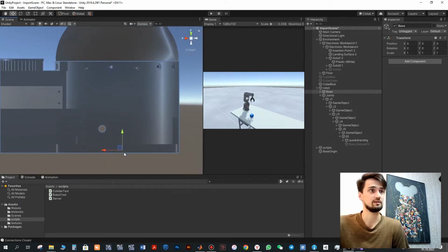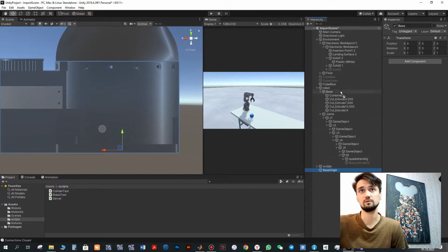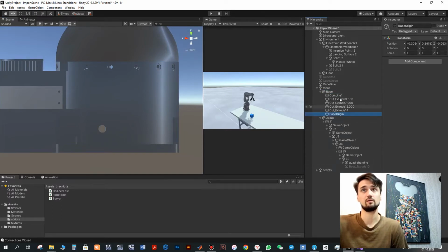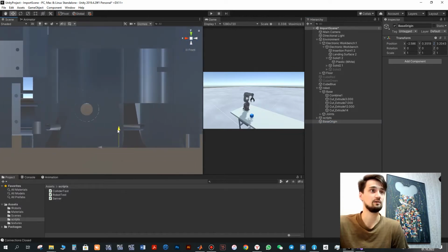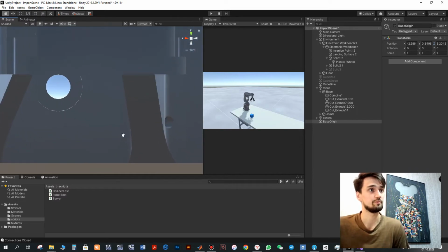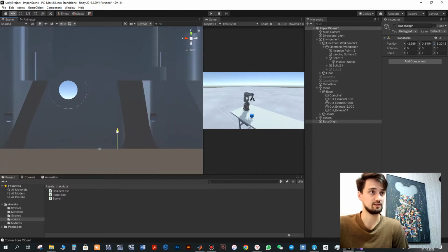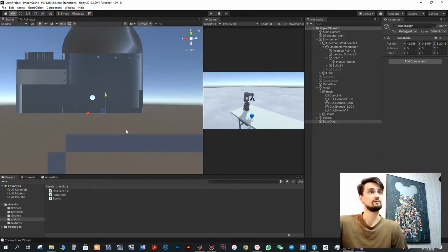It's not exactly here, so I will move it a bit manually. So let's locate our base region here. So I will reset this component 0, 0, 0, and I wanna set up a region for base in the right place. So I move it a bit down. If you need more precise region settings, you can do it with a blender, as was explained in the first video.